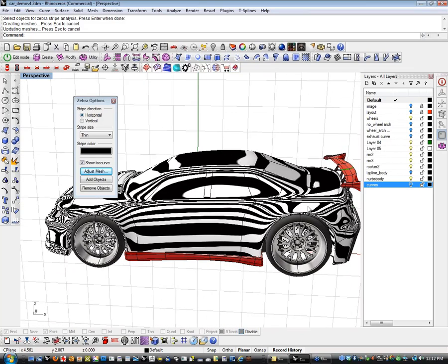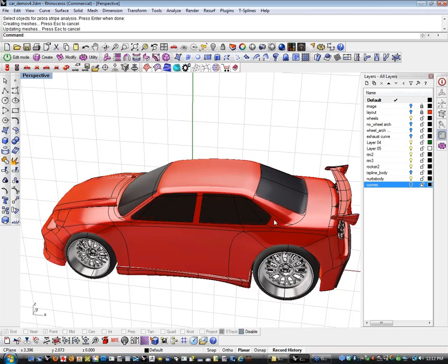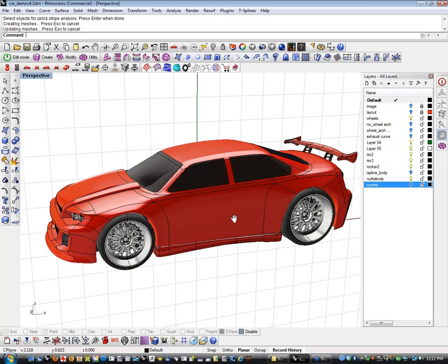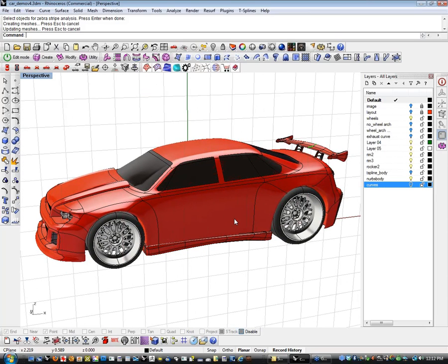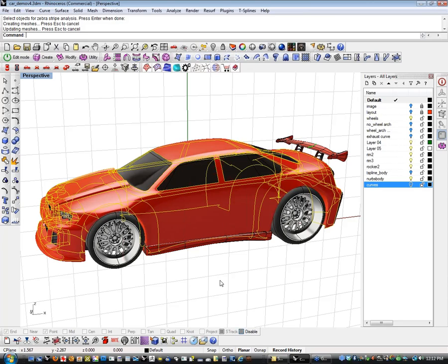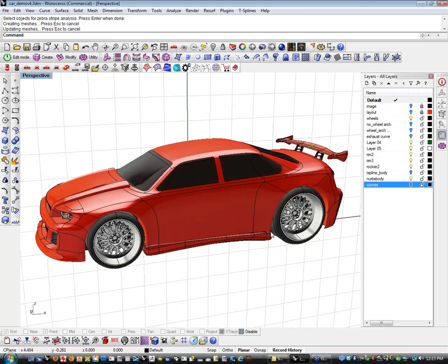Especially this one, this nice little Z highlight right through here, is something that essentially any car that's got this type of pillar situation, you're going to get this highlight back in here, and getting that to track cleanly from one surface into the next is an area of considerable issue. In T-Splines, one of the coolest things that I've found about doing cars is in NURBS, you're laying out big patches, and so essentially you'd lay out this whole body side, you'd lay out the nose, you'd trim out some holes, and then you'd lay out a hood, and then you'd trim that all out, and then you'd spend all the rest of your time trying to blend these things together so that you get that nice clean tracking zebra highlight through there.